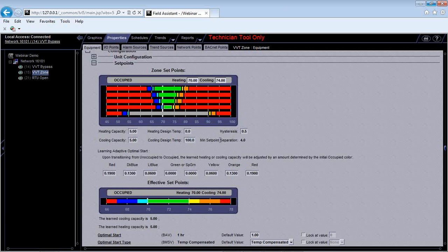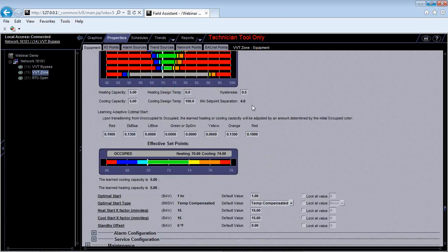And that deadband is there so that you are preventing changeover from heating to cooling mode all the time. Okay, you don't want to be switching. You don't want to be cooling down to 70 degrees, and then once you get below 70, switching right into heat. You want to have a little range that you're maintaining between there. We usually try to do 2 to 4 degrees depending on the application, but it's really up to you what you need to do here with your application.